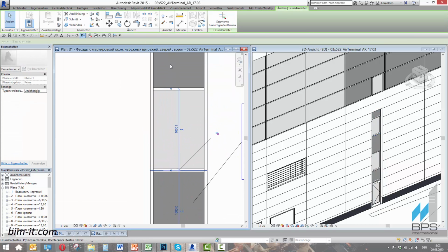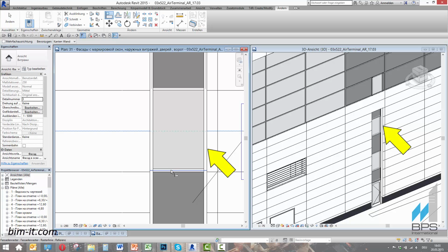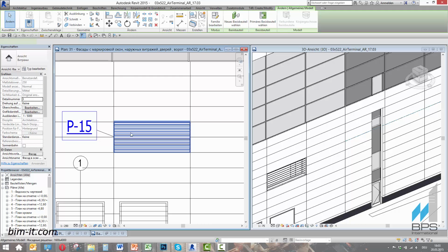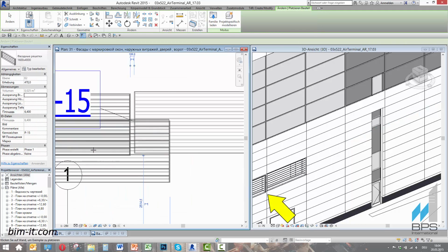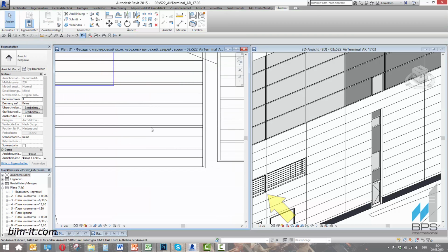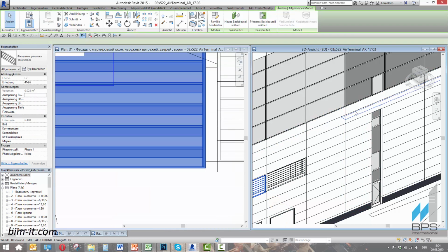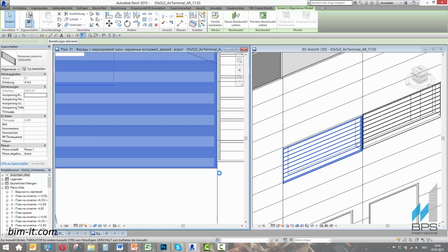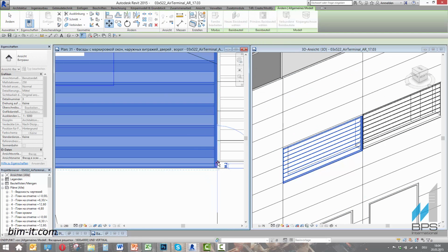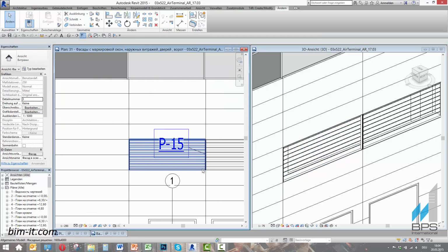Thanks to visual accuracy and adaptive shadows, the informational model detects mismatches and fixes them in all the associated drawings. By installing this ventilation grid into the facade structure, we also create an opening which will be excluded from the facade panel specification and add this grid and its properties into the ventilation equipment list. Now it can be seen and edited on all the project views.